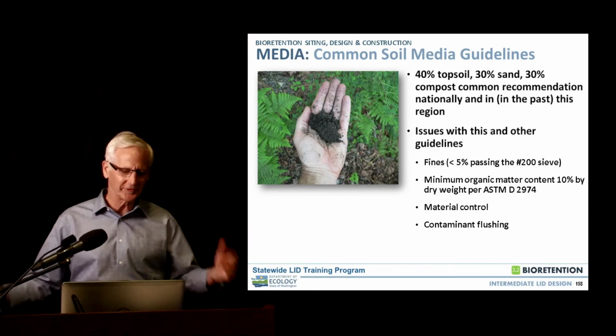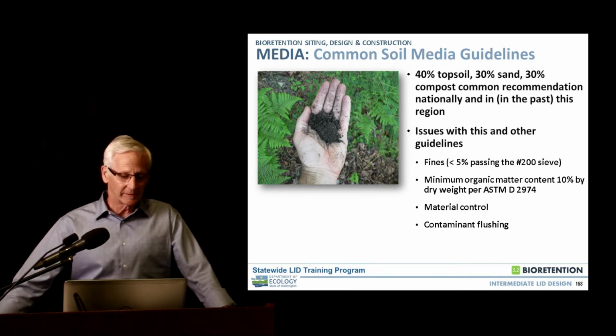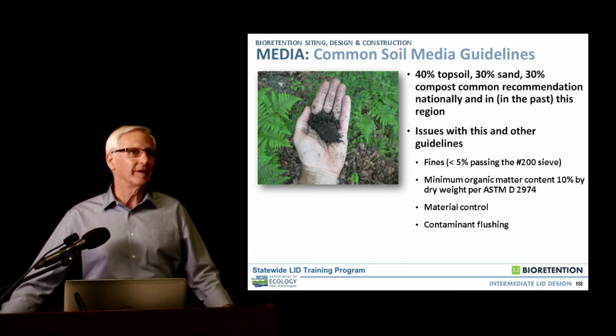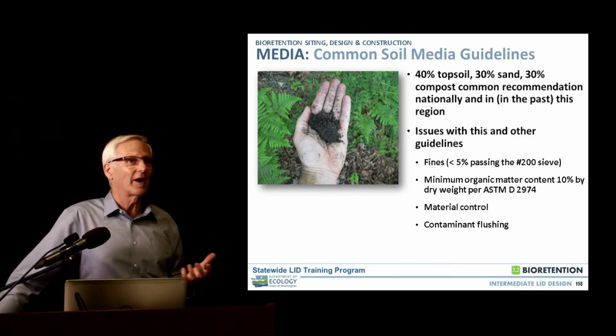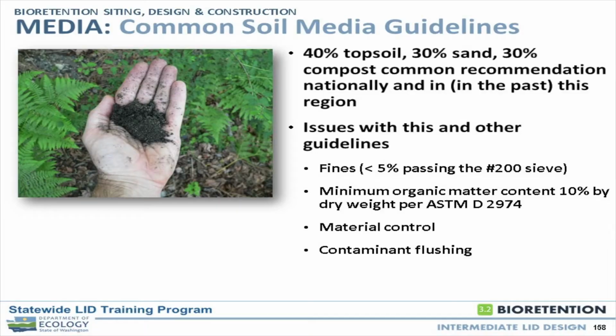We started thinking about these issues long ago, over 10 years ago. Topsoil can have a lot of fines in it, and fines are the mineral particle size passing the 200 sieve. So that's small. That significantly affects your infiltration rates. Topsoil can be well above that. Minimum organic matter content, 10% by dry weight. That's an old recommendation. It's hard to control that with topsoil. You just don't know what that organic matter content is going to be.